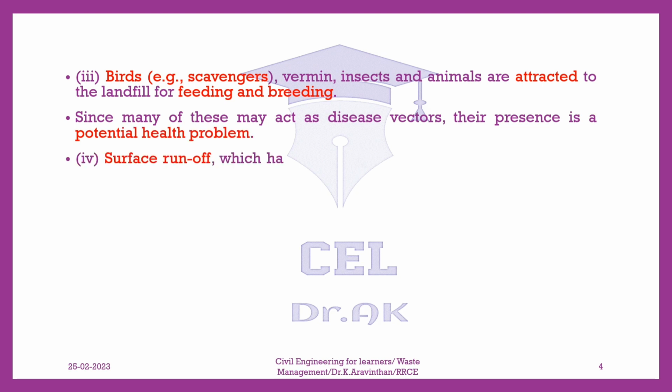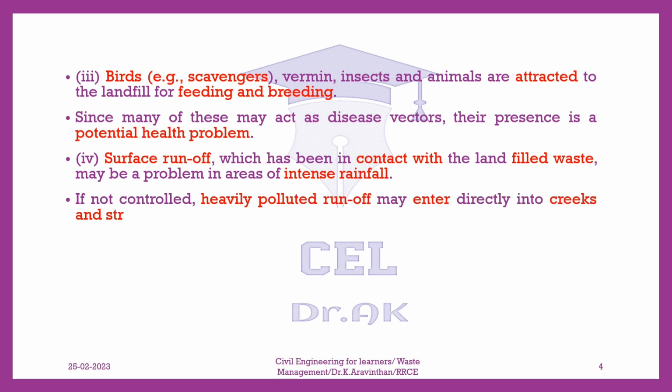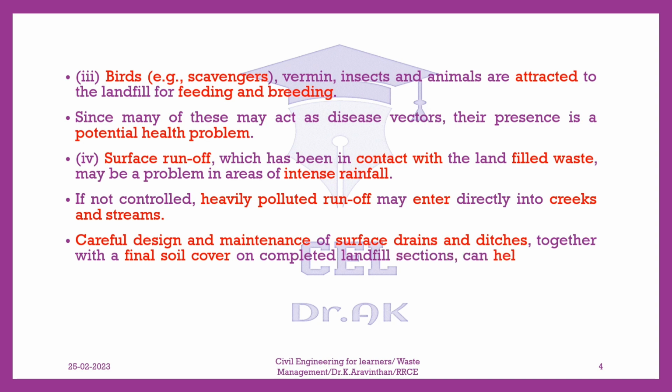4. Surface runoff, which has been in contact with the landfilled waste, may be a problem in areas of intense rainfall. If not controlled, heavily polluted runoff may enter directly into creeks and streams. Careful design and maintenance of surface drains and ditches, together with a final soil cover on completed landfill sections, can help eliminate this problem.